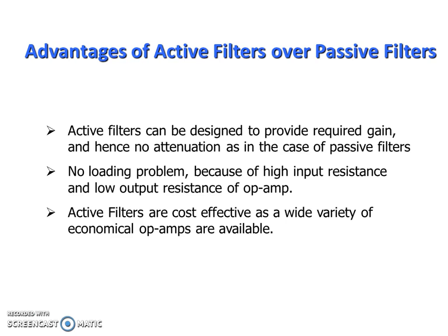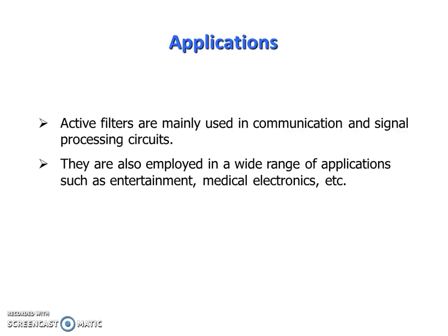and we don't find any loading problem because the input impedance of an operational amplifier ideally is said to be infinity, and practically it will be very high, and the output resistance will be low, which is an advantage of active filters. And active filters are also cost effective.